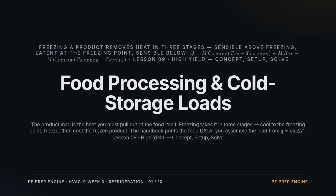Week 3, Lesson 9, Food Processing and Cold Storage Loads. This is the product load, the heat you pull out of the food itself. Freezing happens in 3 stages. Cool the product down to its freezing point, freeze it, then cool the frozen product to its final temperature. The handbook gives you the food data, and you assemble the load from Q equals MC delta T. We'll break down the 3 stages, then freeze a batch of salmon.